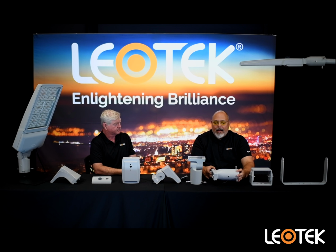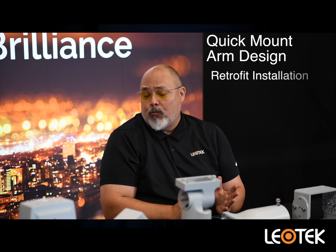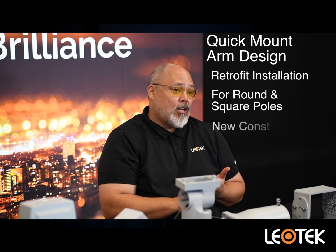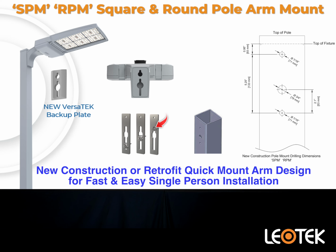Now, the one thing about our square and round pole mount is it's designed to be a quick universal retrofit mount. And what does that really mean? So a lot of our customers and applications are doing retrofit where they're replacing either an existing HID luminaire or replacing an existing LED luminaire. Now, what you don't know is what is the bolt pattern. And the last thing you want to have to do when you install a product in the field is have to drill the pole. It's very difficult and very expensive to do.